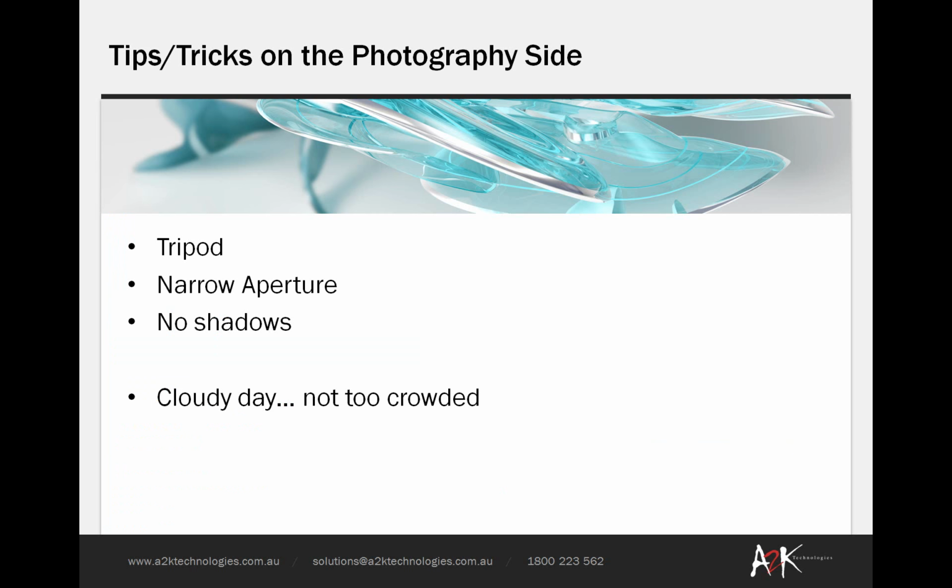So the main art form of this is taking the photographs correctly. The rules are you must have a lot of overlap. You want to take a bunch of shots of the same geometry and make sure you're not standing in the same place. You must move, so each shot comes from a different angle and lets the software triangulate.